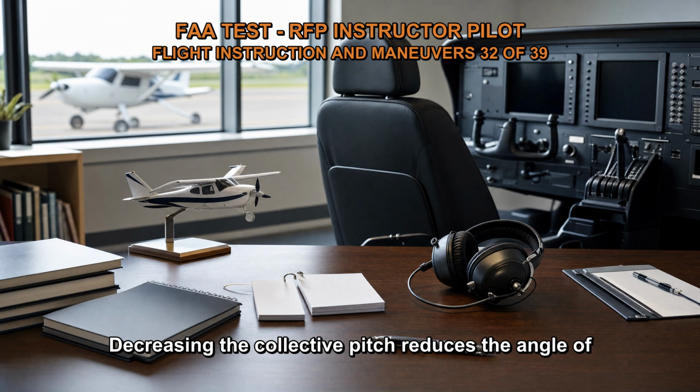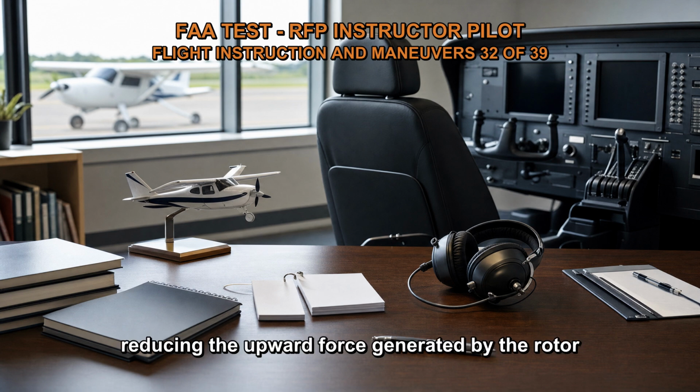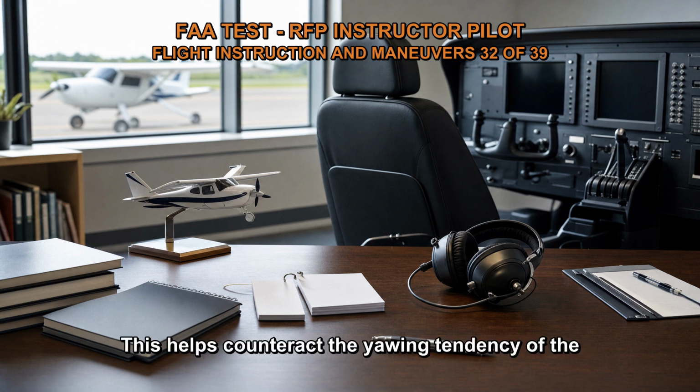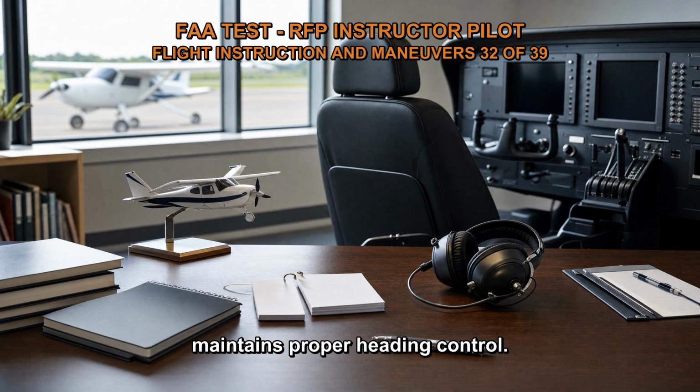Decreasing the collective pitch reduces the angle of attack of the rotor blades, resulting in decreased lift. This action helps in the rapid deceleration by reducing the upward force generated by the rotor system. Applying right pedal: the pilot should apply right pedal input to coordinate the deceleration maneuver. This helps counteract the yawing tendency of the helicopter during the deceleration, ensuring that the helicopter maintains proper heading control.